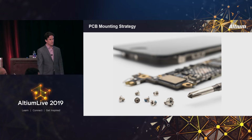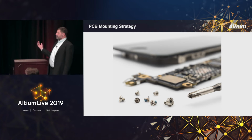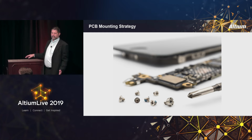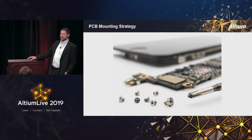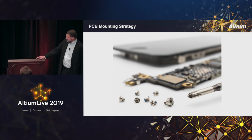Yeah. So also, are you going to plan on having a perimeter of ground vias around the board? These are EMI considerations that should be dealt with at this stage. You should know when you start the design, do I need to have a ground ring around the outside of the board? Are there any... we're going to get to shielding next, I think, right?